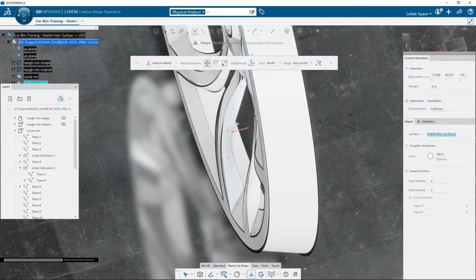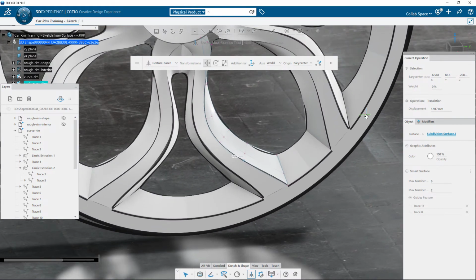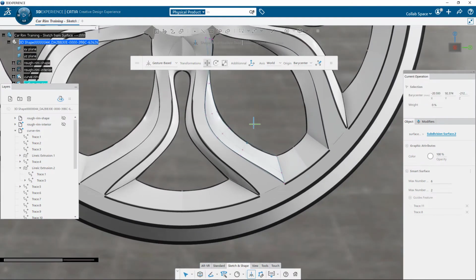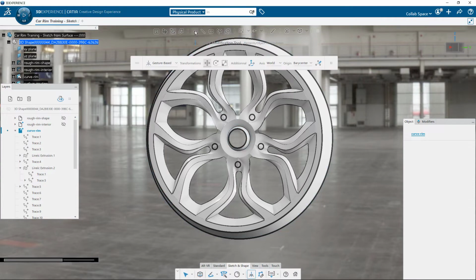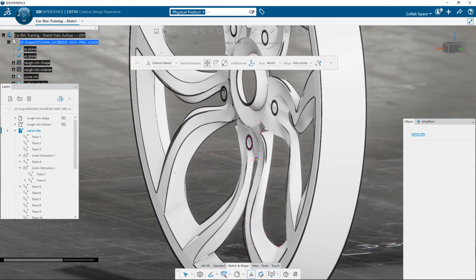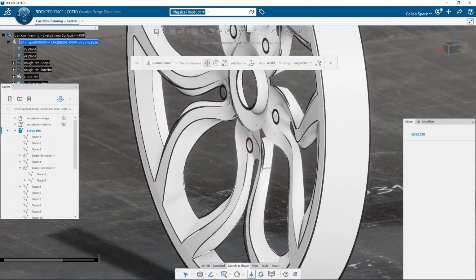Even if I manipulate the surfaces with its base mesh, there is still associativity between the original curves and the surfaces created from it. I am able to modify the curve shape and the surface will still be updated to follow the modifications. Here I start to have a lot of objects in the 3D view, so I use the object filter located on the left of the option bar to filter selection only on curves in this case. When I go back into the Transform command, only the control points of the curves are visible, which prevents me from using or editing the base mesh of the surfaces.